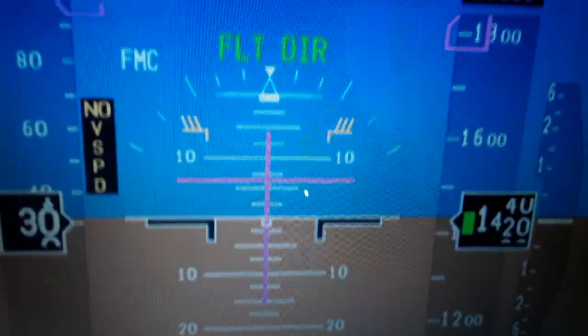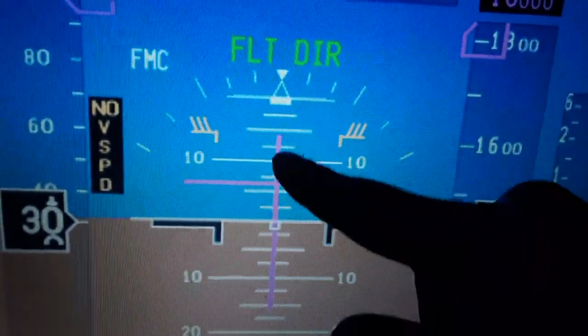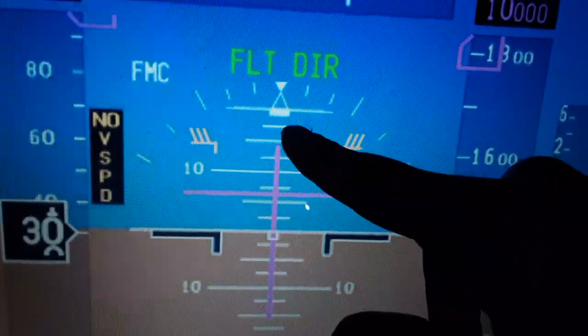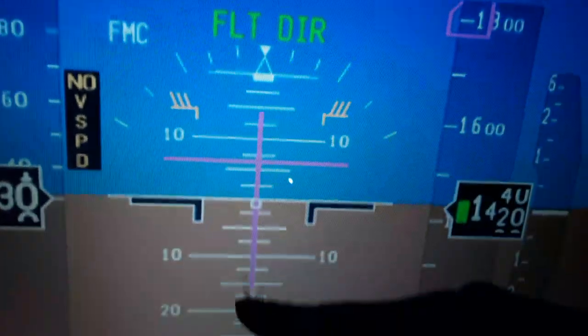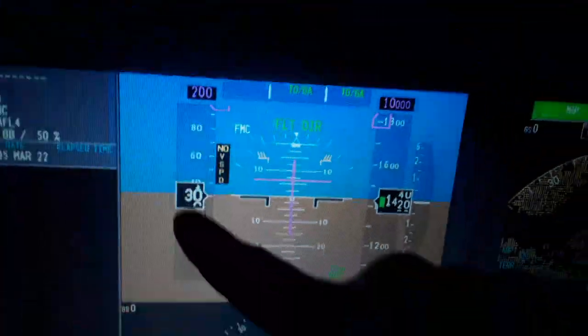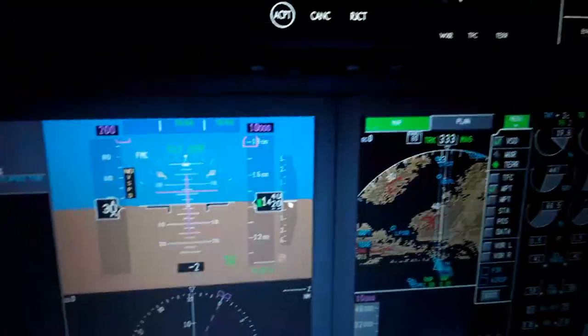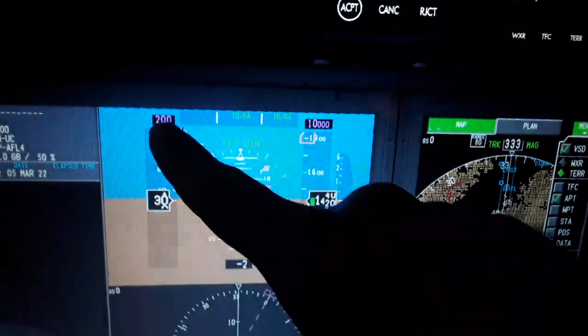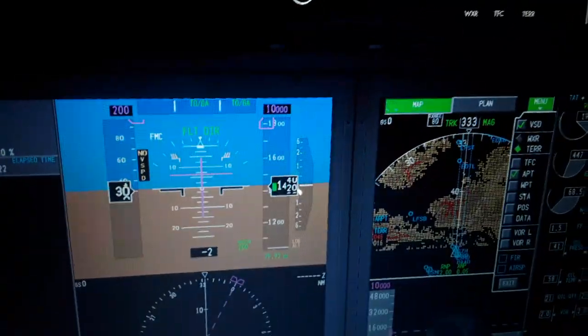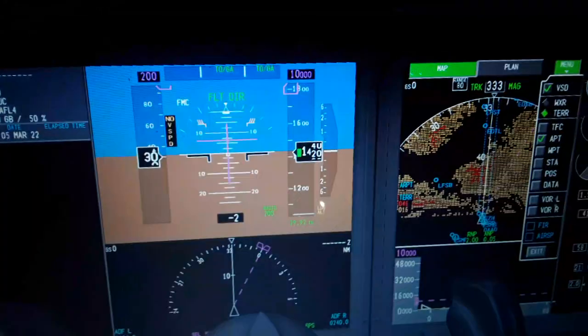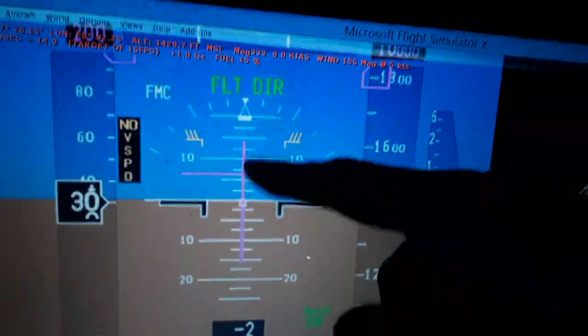So we have the pitch lateral degrees. You can see 2.5, 5, 7.5, 10, 12.5, 15, 17.5, 20 degrees for pitch up and pitch down as we fly the aircraft. You will see also the stall speed displayed with the amber and red. Also the flap limit, the never exceed speed, maximum Mach operating. So we have also pitch ladder in degrees, like 20 degrees up and down.